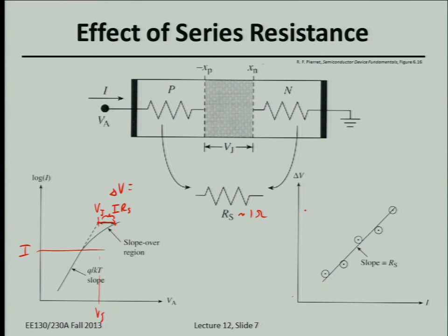So in a manufacturing process, we actually put it into a furnace or uniformly illuminate the wafer with light to heat it all up at once and bring it all down. If you locally just heat it in a device, then you're not going to get nice uniform dopant activation and recrystallization.